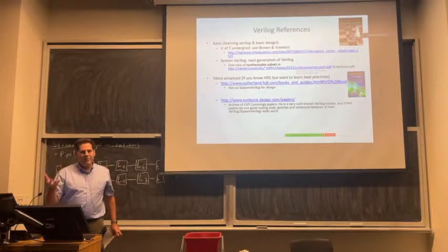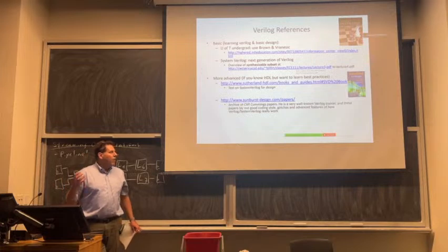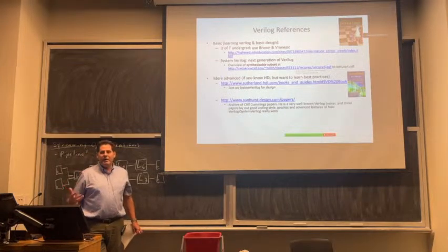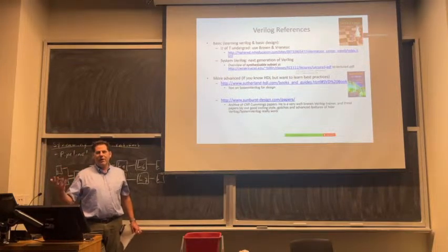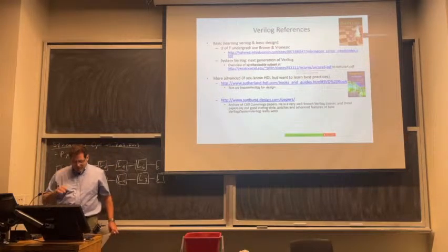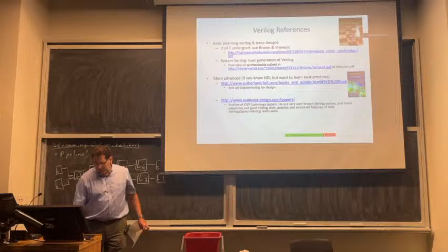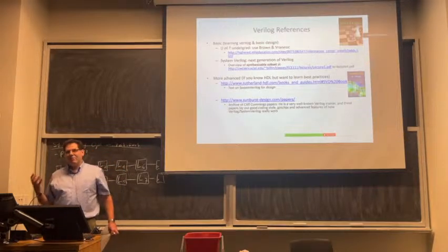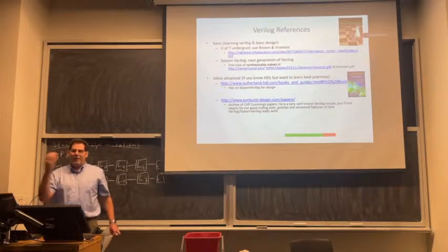You could simulate any hardware you wanted. Only a subset of what you can write in them can actually be automatically synthesized or turned into hardware. And that subset was agreed upon by convention, because it wasn't what the languages were originally designed to do. So these lectures cover the most important part of SystemVerilog, in my opinion, which is the synthesizable subset, the stuff you can write that will actually turn into hardware.